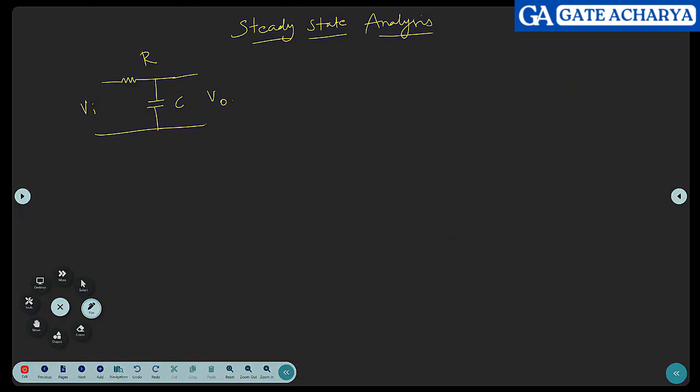The steady state word is, if you read very good books, they usually attribute this to a word called time harmonic. Why do they do this? Whenever you use the situation of steady state, you can take Fourier transform. That is a frequency domain, you can push it. You can push a time domain equation into a frequency domain whenever they say the word steady state.